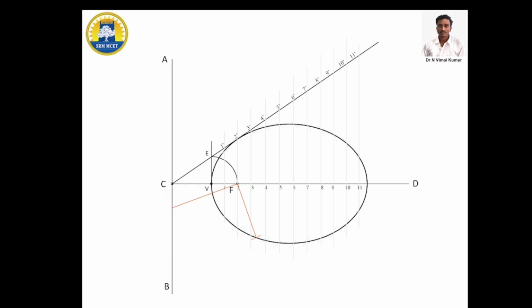From the center point F, take a 90-degree value and put down a straight line. This is the straight line. Then notice this point and this point. This is the focus point to ellipse, 55 mm. This is the tangent point. You should connect this straight line. This is called the tangent line.